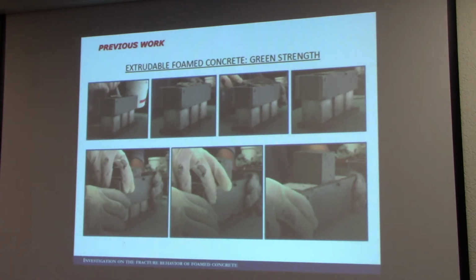And we demonstrated this particular advantage by simulating an extrusion production process, with a very simple hardened cubic specimen that pushes a fresh state paste. We noticed that the fresh state paste did not expand laterally upon pushing the specimen. And this was also demonstrated by other tests that we performed with the robotic arm. Based on these encouraging results, we are working on this new field of application of foamed concrete that can speed up the production process in the construction field.